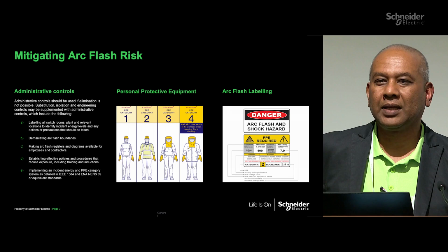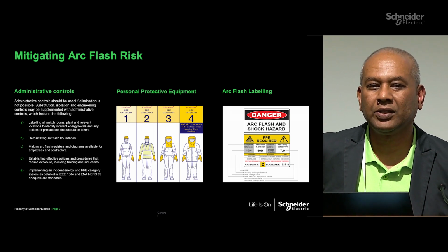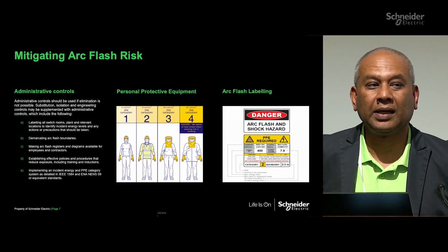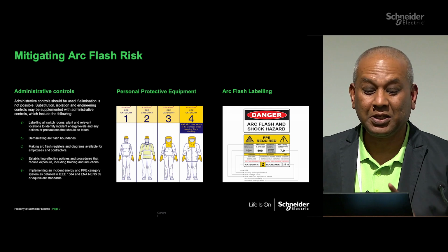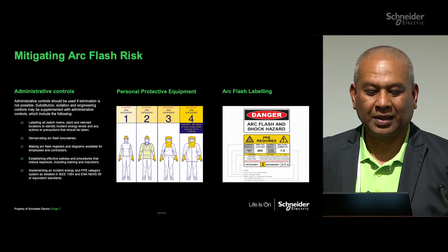If the equipment is as we have tested it for the arc flash or the internal arc rating, then you don't actually need to worry about wearing that. If you calculated Cat 4, but it's in this normal operating condition, you don't need to wear Cat 4. I mean, your Cat 1 will be fine, right? The reason being you haven't opened.